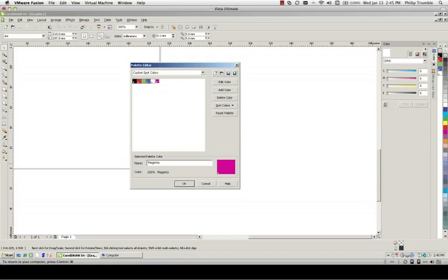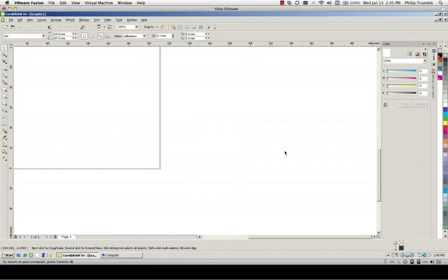You click on the color, and the name is magenta. We need to change that to Cut Contour, but you need to spell it exactly as I spell it here. Capital C U T, capital C O N T O U R. Cut Contour. Make sure that the capitals are in the correct place, then click OK. If you move your mouse over the color, you should see that it will pop up with Cut Contour.